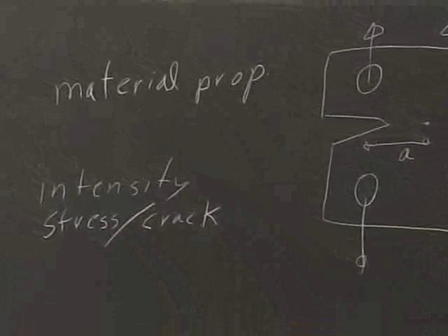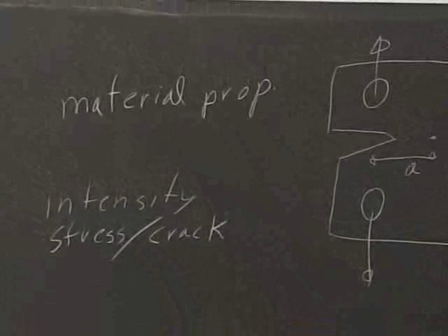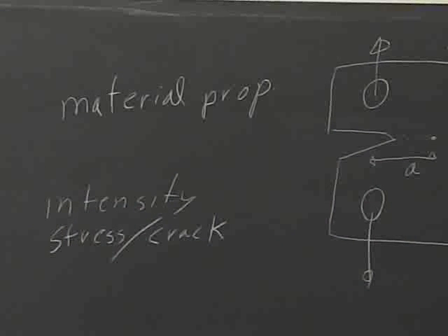Now, if we move away from this idea that we're pre-cracking and we know the crack length, here there's a lot that we need to know. We need to know our loading ratio, we need to know our geometry, crack length, and the material property here, K1C. When I say crack length, it really means something, because a lot of times you hope to make a product that doesn't have cracks in it. So if you have to make the decision, what's the worst product I'm going to make, it's hard.